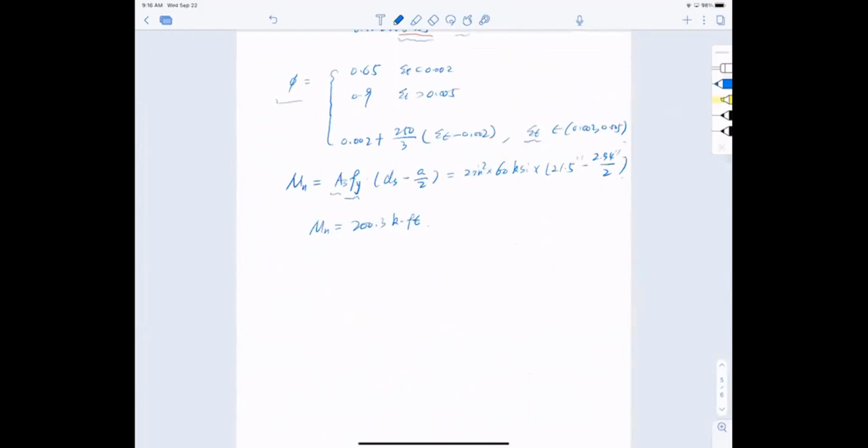Okay, save you the time for calculation. Always check me whenever you can. And then with that number, I can get my design capacity. So for those of you who have forgotten the terminology, this is design capacity, okay? Design capacity or design moment resistance or design flexure strength. So whatever you call it, but this is design. Whenever you see design, that is after factor, right? After the strength reduction factor.